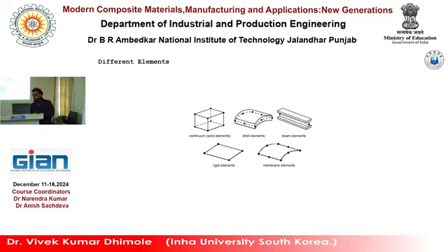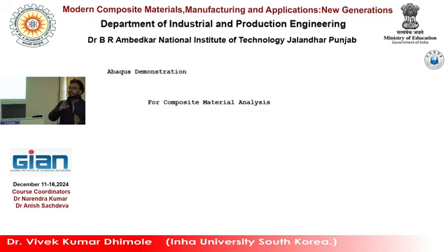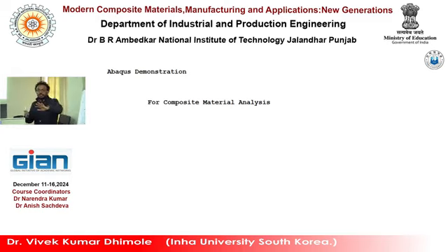Rigid element we have. The rigid one means when we have an impact testing of composite, then we don't need the analysis of that element. Rigid one is a Young's modulus that is very high, right? That means we are not taking the part of that model, the rigid material, into the calculation. It's just the process for the other part. It's just impacting or holding the part, right? Like that. But we are not analyzing stress on that part. Means those parts are not under the design consideration.